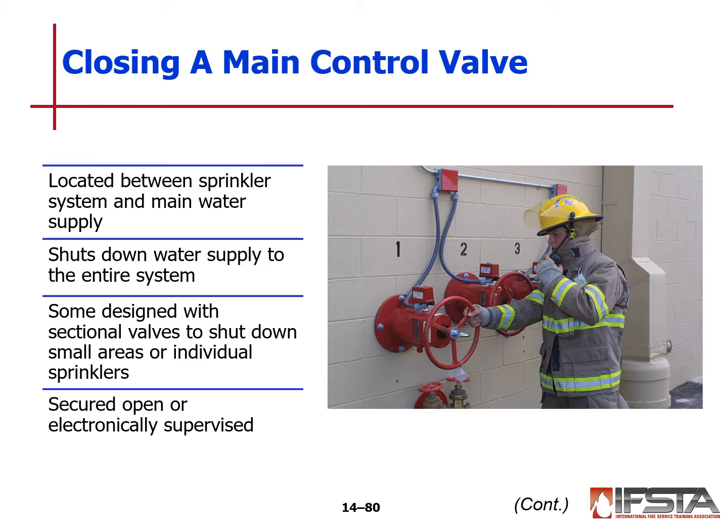And these are secured in the open position and oftentimes are electronically supervised. So they're locked open and they have an electronic circuit that, if the valve were closed, communicates that to the control system and the alarm system, and it will alarm to let you know it's been shut down.